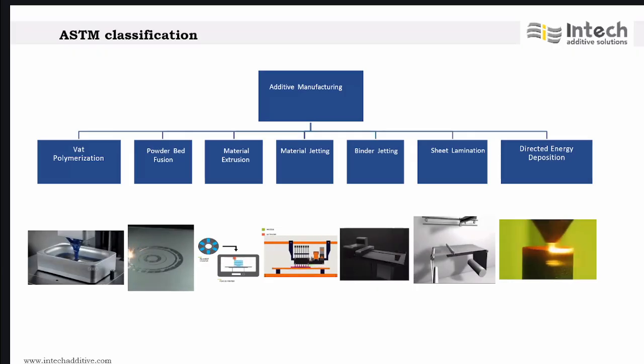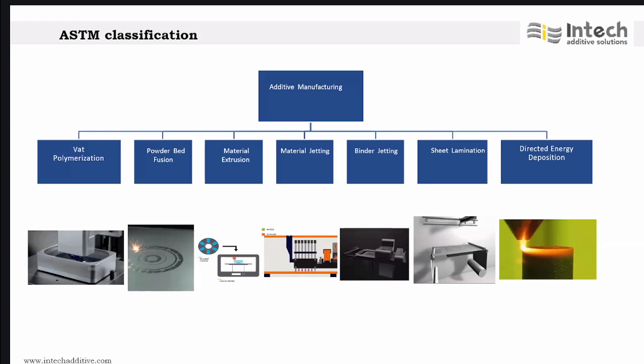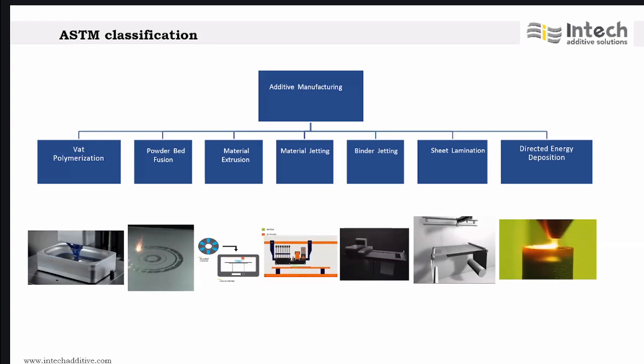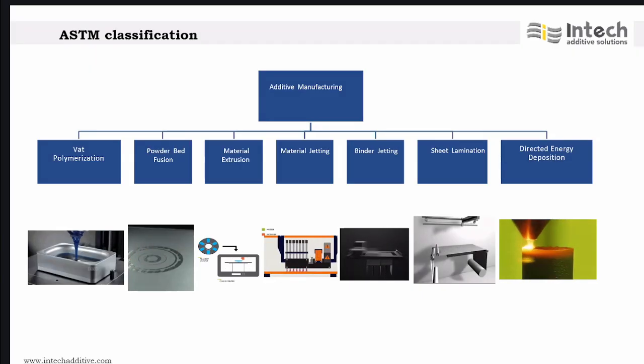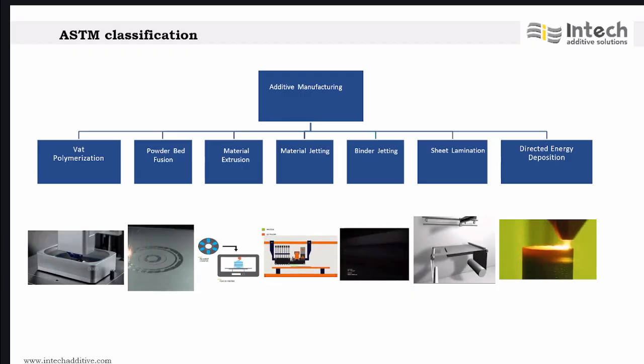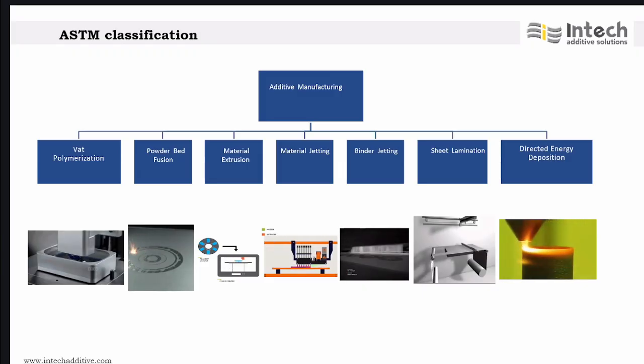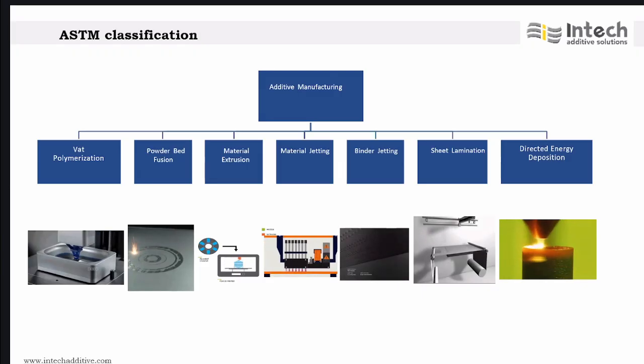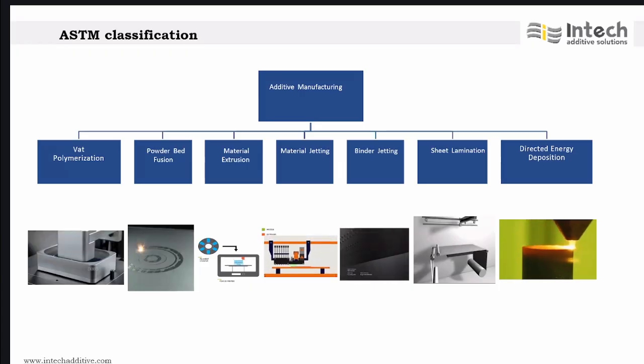The material that is used in binder jetting is sand. You can use metals, ceramics, and also some polymers. It's best for making sand casting molds, and metal parts also you can make. And like I said, you're using liquid binders, so you can bring in colors. So full color models you can do, and architectural models.